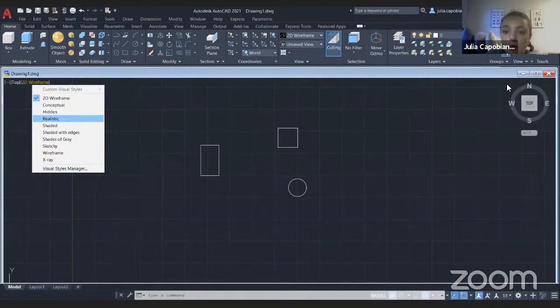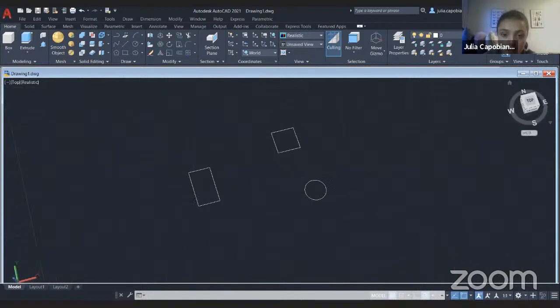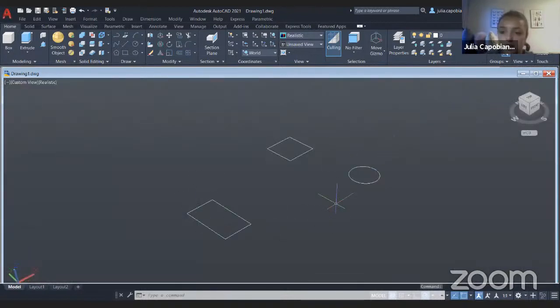So what we want to do is change the view that we're looking at so that when we actually make them 3D, you can see the height that's changing. You can go to this top right coordinate system and go to the home button and it'll make it view from a southwest angle, which is, you could imagine when you make something 3D, you could see the height changing.